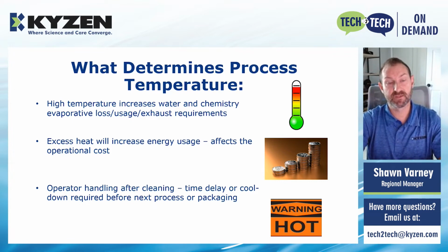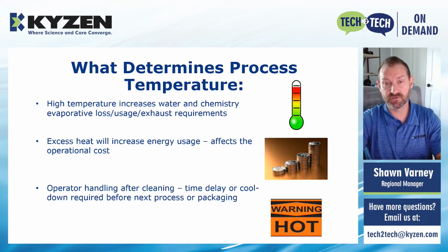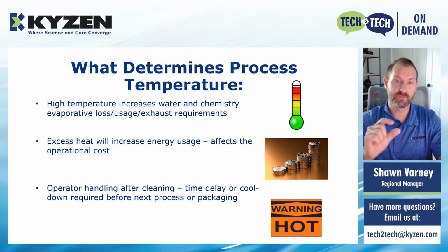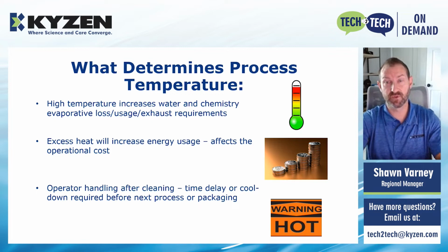Excessive heat will increase your energy usage and affect the operational cost, of course, as you increase that dwell time and you want that temperature to go hotter. Of course, you're using more energy with it, and you get a little less green. You want to watch your temperature settings to see how they affect cost with your heaters.